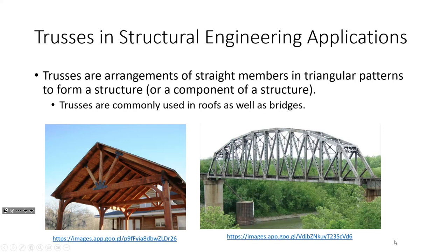One, trusses by their very nature tend to have potentially sloped roofs, which allow for drainage of rain, so we want that slope whenever feasible. But second, architects tend to like really open spaces. So there's another challenge where you want a really, really large span. You need a structural element that can resist that span. That's where trusses come into play.